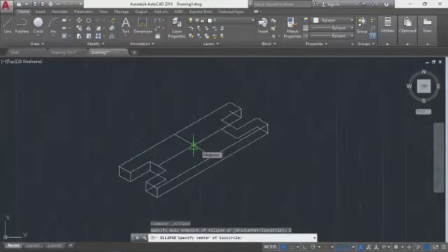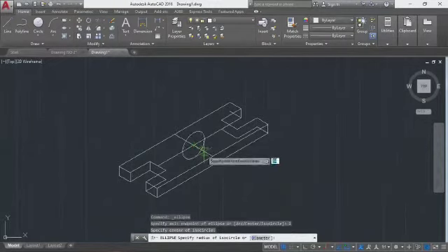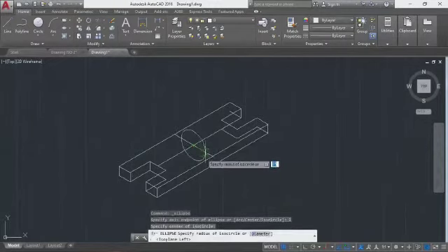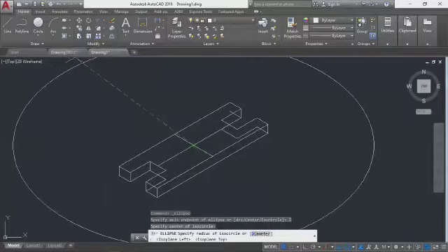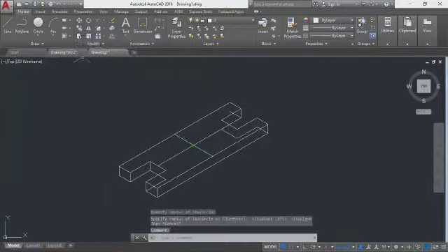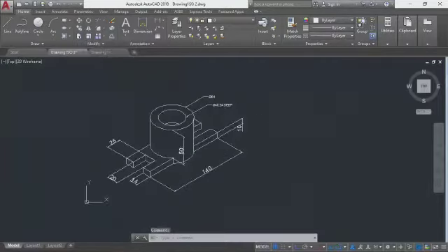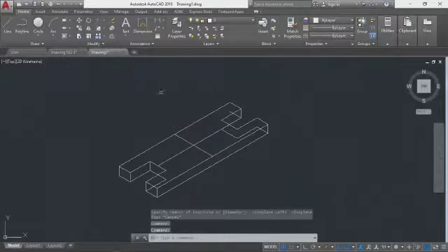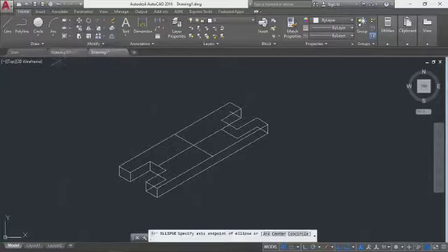You see, you can now change your cursor. Let's go and check the radius over here. What radius does it have? Let's check. The radius it has is what? It has diameter 64, radius 32. If you have diameter 64, radius 32. So let's go back to our diagram and pick our axis point, isocircle. Then you come over here to pick the point.